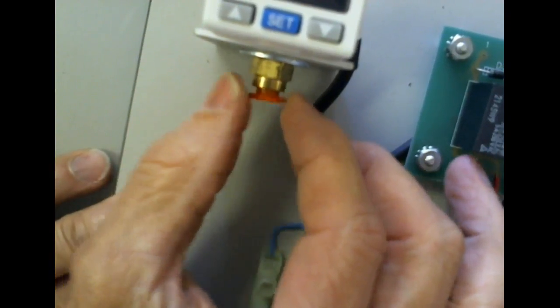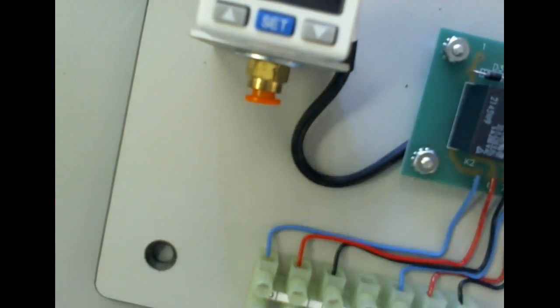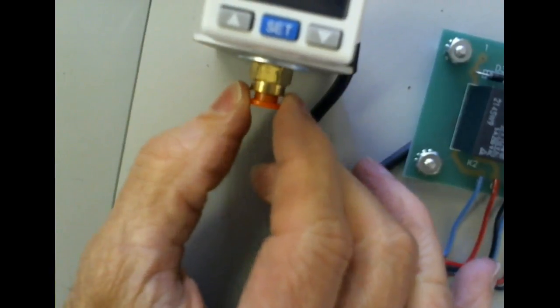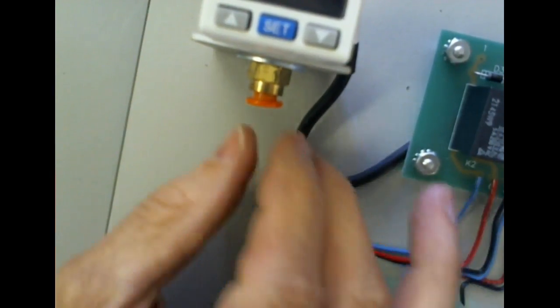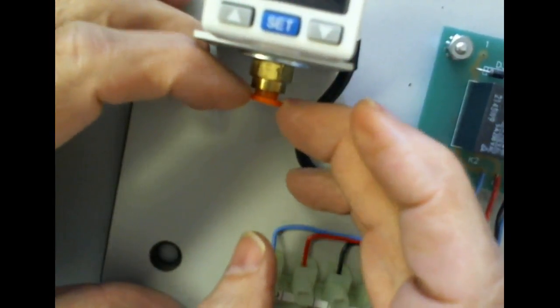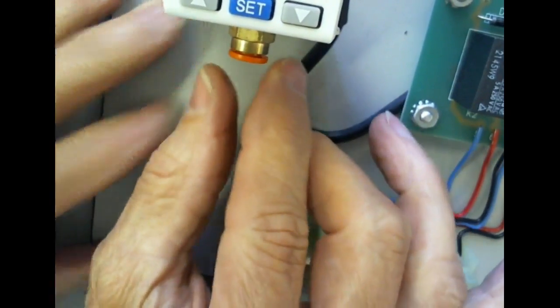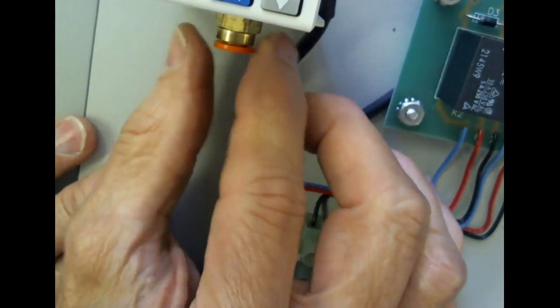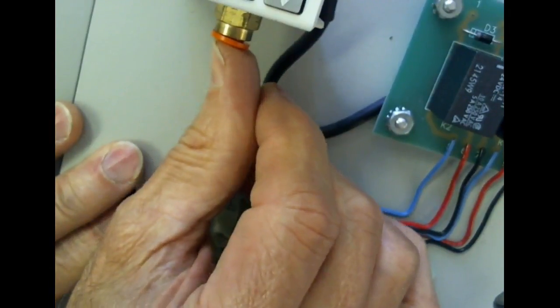By the way, this is what's nice about pneumatics. Pneumatics run at such low pressures that instead of using metal tubing or reinforced piping, we can actually use plastic. These are quick disconnects right here. To get it out, you have to pull this down, and that releases it. It's got some fingers in there that grab the tube. When you push it in, normally we push them in, but when the pressure comes into the system, it'll come up and seal it in, which is pretty neat.